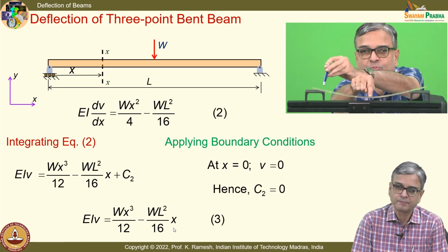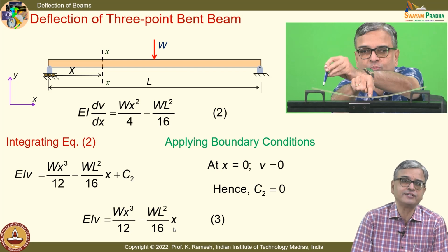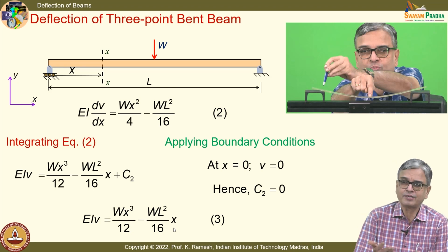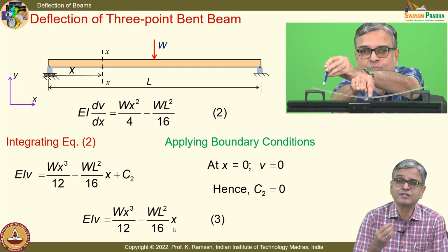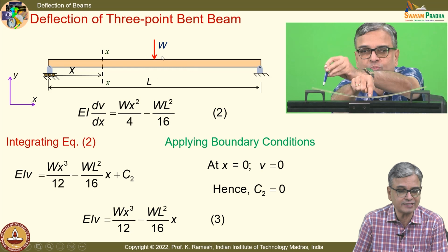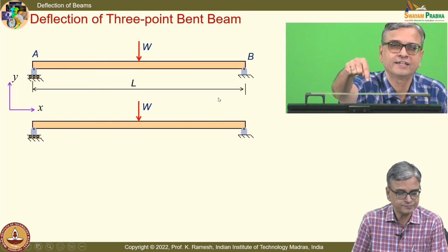Okay. See, I have also been saying that certain quantities you need to remember as part of this course. Even after you complete the course, when you have to apply this knowledge in the field, you will have to remember this. It makes your life a lot simpler. We will have to find out what is the maximum deflection at the load application point. That is a very important answer. So, you are going to substitute x equal to L by 2.